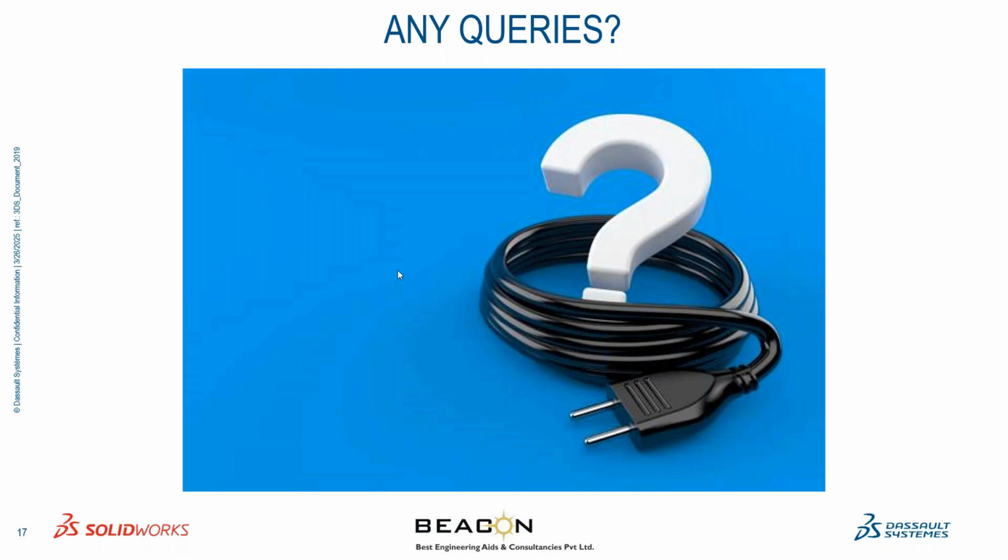Right? Mr. Saravana Raj has asked if a field wiring diagram can be created automatically. We do have terminal block creation from scratch. So if I have created terminal X1 in one page, X1 1 in one page, X1 2 in one page, X1 3 in another page, I can get an automated drawing of the terminal X1 with all the 1, 2, 3 in the same diagram. It will automate and give us the diagram.